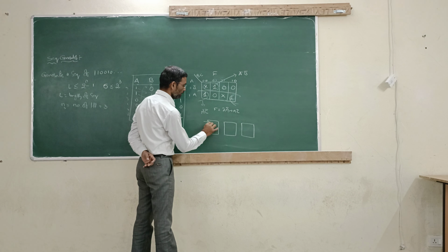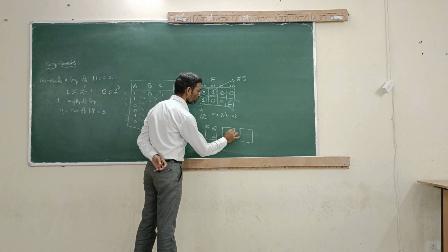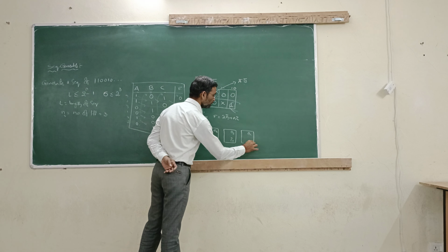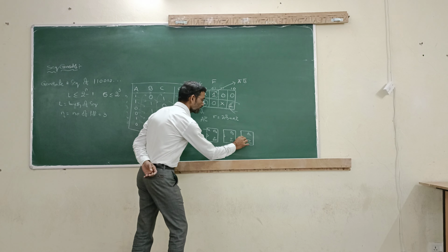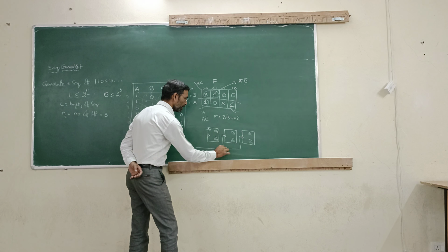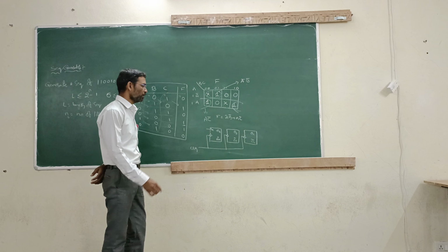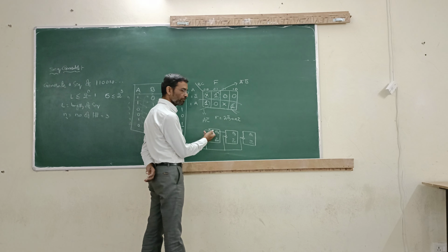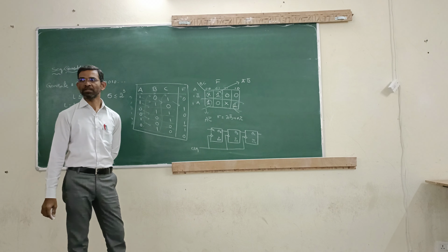Each is going to generate two outputs, QA, QA bar, similarly QB, QB bar, QC, QC bar. Here we are going to use a negative edge clock signal. We have to connect all 3 flip flops to a clock signal. We give the QA output, that means the first flip flop output, to the second flip flop. Similarly, the second flip flop output goes to the third flip flop.